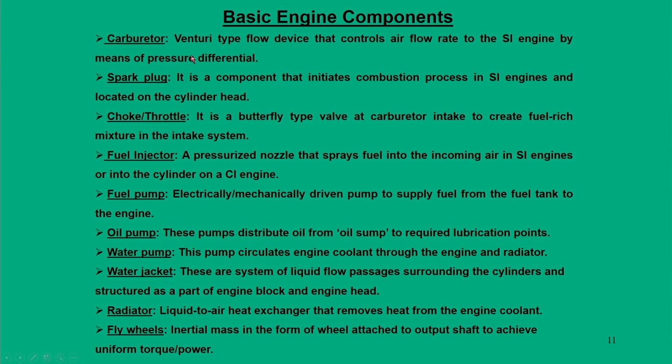I can just spell out some of them. We have a carburetor. It is nothing but a Venturi type flow device that controls the air flow rate to the SI engine. In fact, the carburetor is the main component for an SI engine, and essentially it gives a pressure difference so that the intake air enters into the engine.